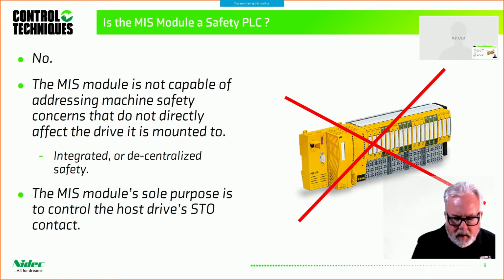A question I had when I first started looking at this particular module, and I've been in the industry for quite a while, and I've heard of machine safety, I've heard of safety PLCs, I've heard of safety controllers. So when I first looked at this module, I thought, gosh, is this a safety PLC, or what is it? And the answer to that is no. It certainly is not. The MiS module is not capable of addressing any safety concerns that do not directly affect the drive it is mounted to.